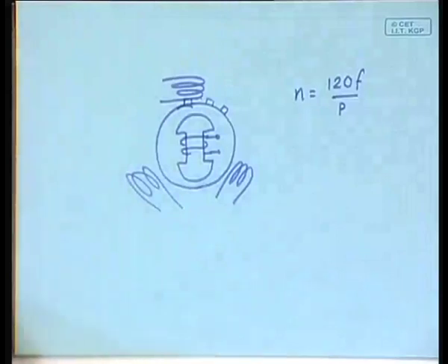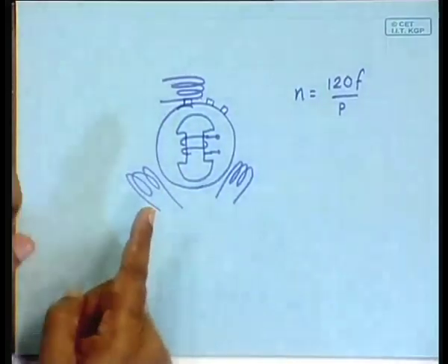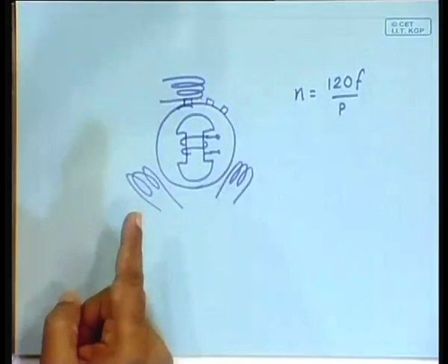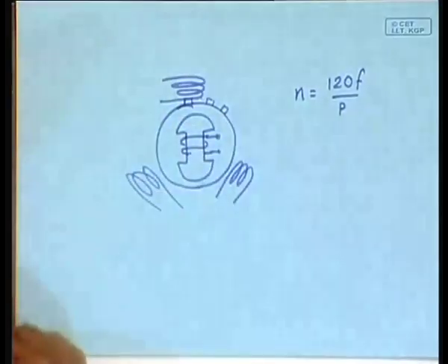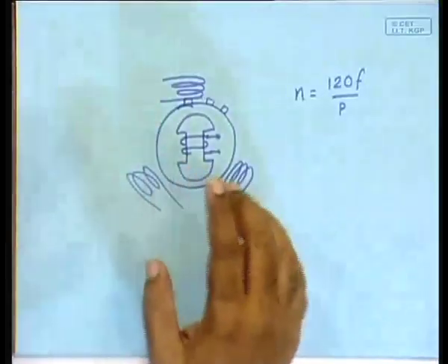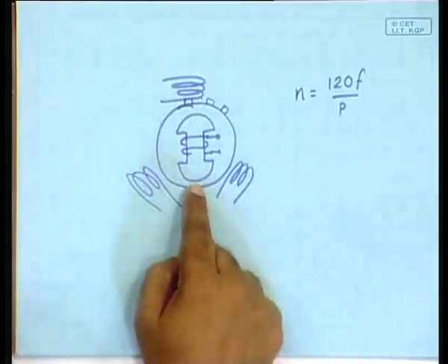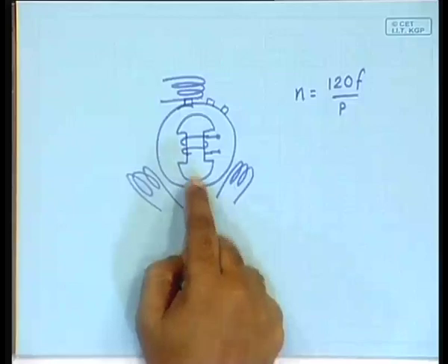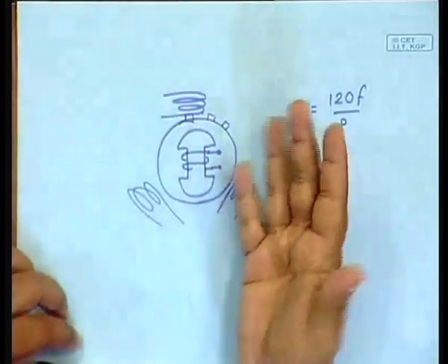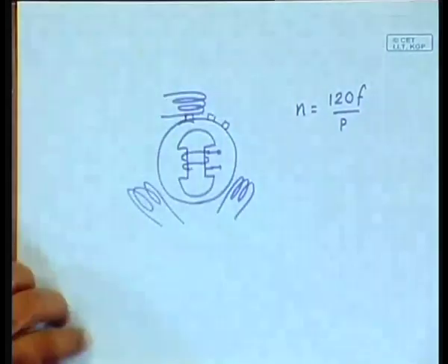What is the concern is that in that case, in order to generate a constant frequency, I need to rotate it at a constant speed, and our supply is constant at 50 hertz. So, if anything is to be hooked up to the power supply grid, then it must generate 50 hertz, which means the synchronous machine should, not should, must rotate at a single specific constant speed, right. Let us see, does this character match with the character or required character of a wind turbine?